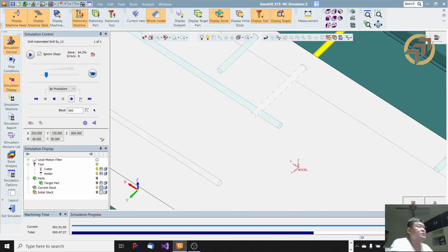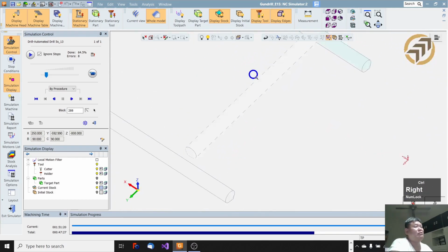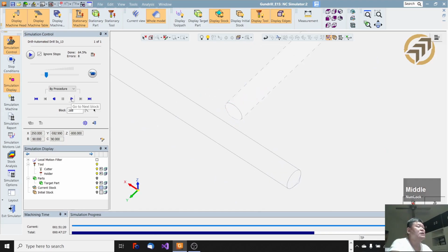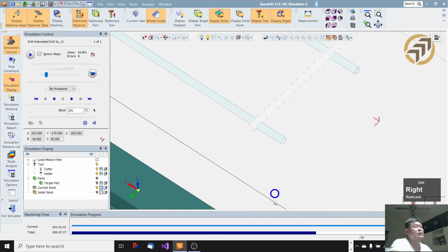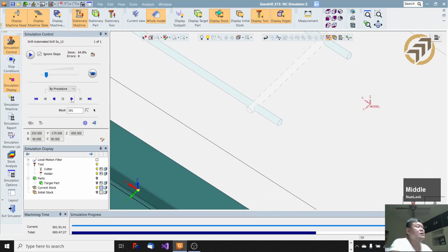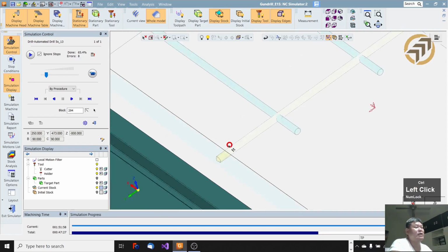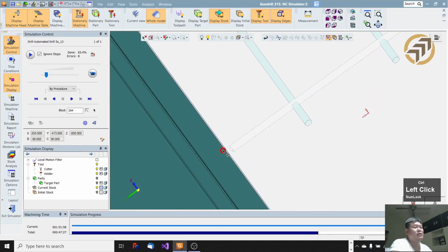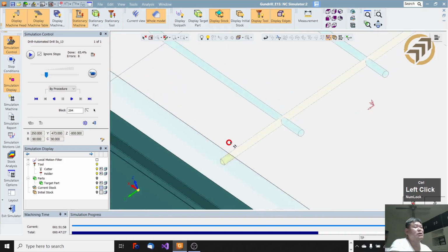Again, there's a cross hole here, so 100% until 5 mm before the cross hole. Then change the feed rate to 50% and continue drilling until 5 mm after the cross hole. Right? And change to 100% feed rate, drill until 5 mm before the tool break tool.